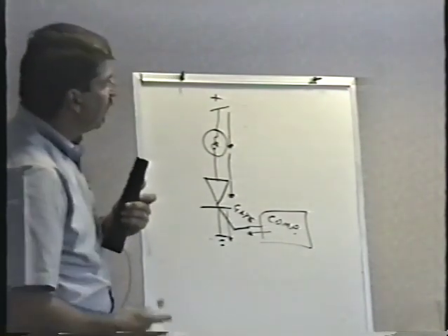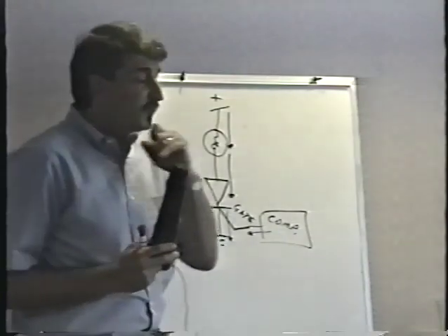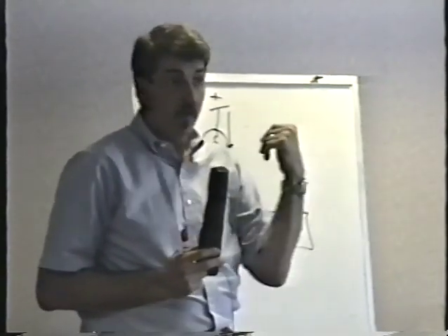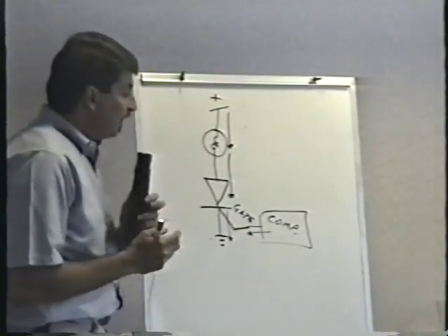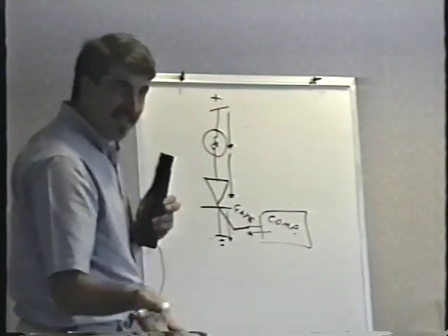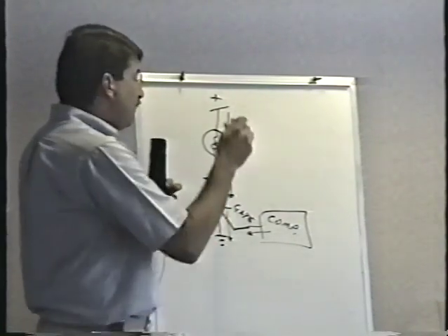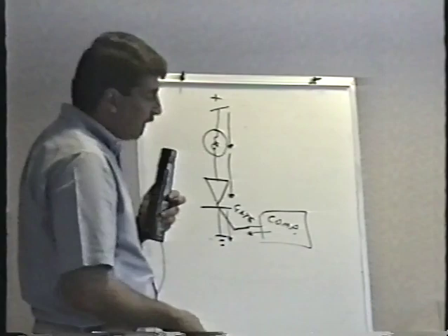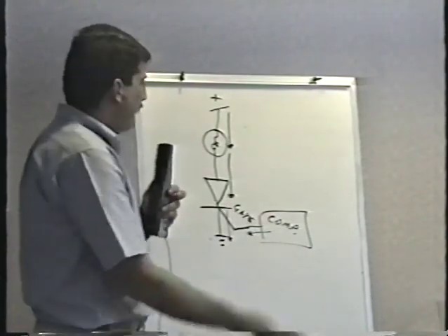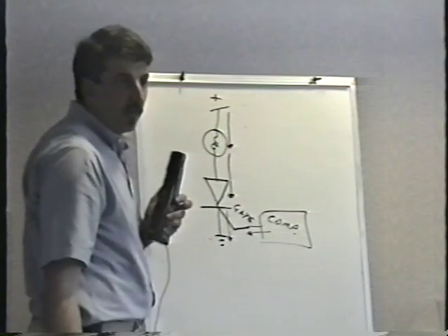Well, troubleshooting these things is pretty easy. There's not a real transistor type test that I can show you on this. Not really. In fact, the only junction drop you get is from gate to cathode. But it isn't necessary. It was never necessary to test the SCR, because if you had a lamp that never lit up, the SCR was bad. If you had a lamp that stayed on all the time, the SCR was bad. That's all there was to it.